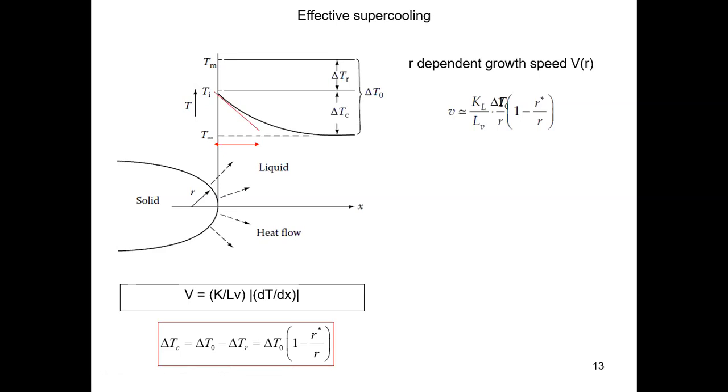So this means that you need to have a delicate balance, and if we do a rigorous analysis to find out what is the local maximum for this growth velocity with respect to the radius. How would you do that? How would you find out what is going to be the maximum growth velocity and the corresponding critical radius for that maximum growth velocity? Take the derivative. Yeah, take the derivative of this guy.